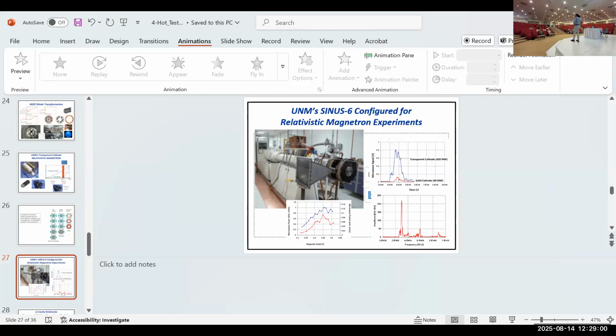Is the number of electrons emitted by the cathode not proportional to the cathode surface? Why is the cathode surface not corrugated? There are a couple of studies on shaped cathodes, with corrugations. But if you have a corrugation, you still have a conductive material, so the radial component of the applied electric field will not be maximum at the surface, because it goes to zero on the corrugation.